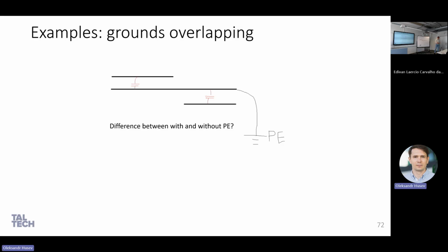No impact. It's overall reducing the D, because capacitance is inversely proportional to the distance between the layers. If we are keeping a common layer, we are decreasing the effective D, and if we are decreasing D, that means we are increasing the capacitance between the windings. So, no, but look, okay.